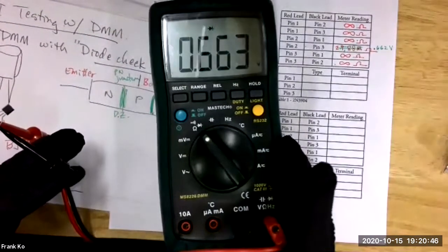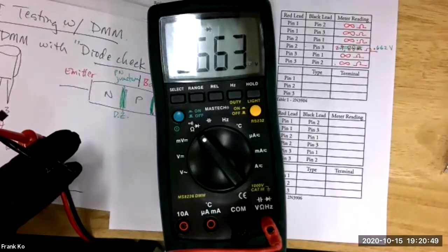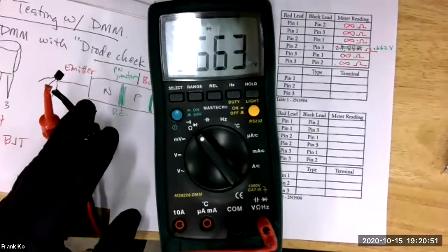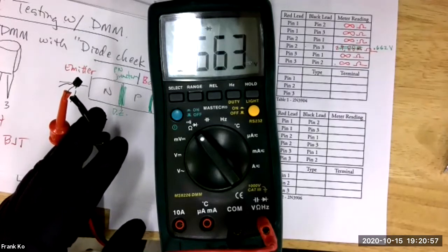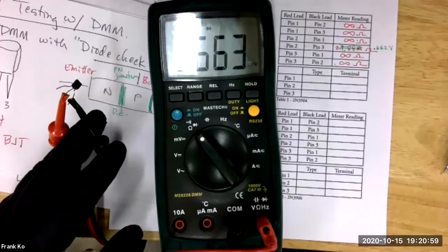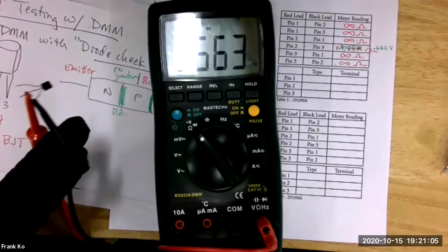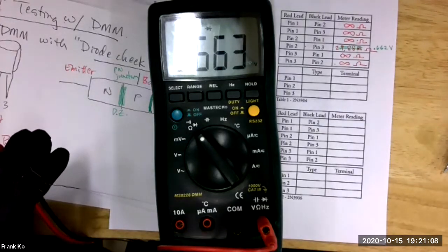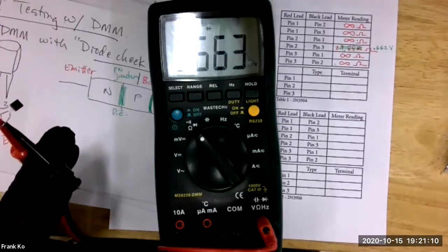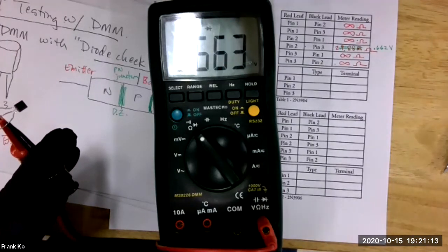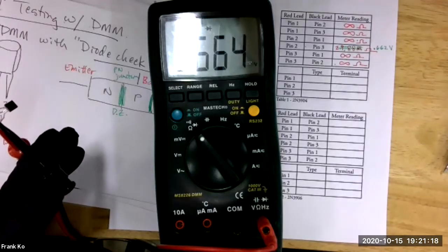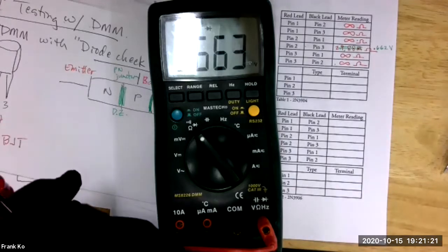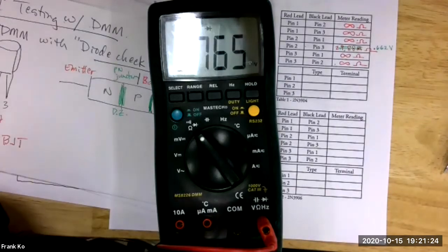Now it barely came back on, so I got 38.6. No, we need you to press the select button until there. That's the diode check. You see the diode symbol at the top? Okay. What is your voltage? 0.636. Okay, that's what you need to record for pins 2-3, yes? And Carlos? Good. Okay, record that.